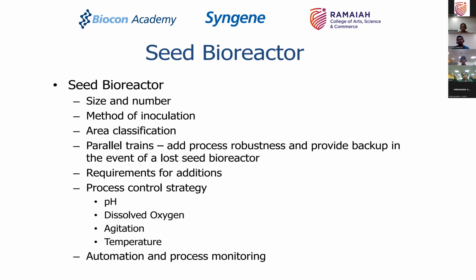And during this entire period of production, you need to maintain the pH constant, because as more and more microorganisms are produced, they will also have an effect on the pH. They are like human living organisms. They will have secretions, they will have excretions, and those will vary the pH. So you have to keep on making sure that the pH is in the right range, so that the product or the cell of interest is growing in that pH. If the pH varies, the cells could start dying.